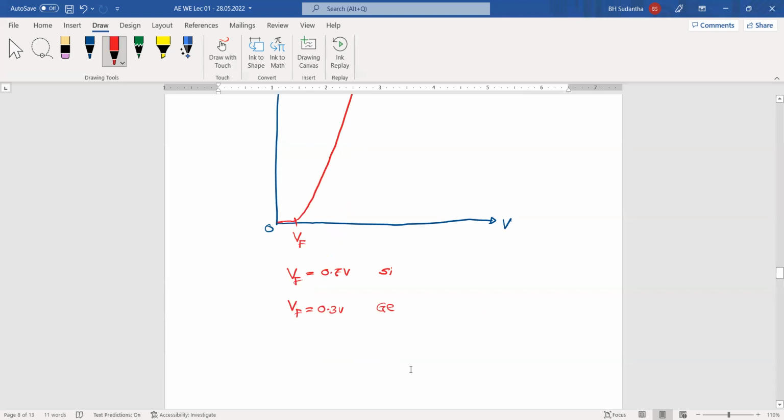You know that using silicon and germanium we can make both N-type and P-type semiconductors, and we can make a PN junction using these two types of elements. The silicon semiconductors and germanium semiconductors have very close characteristics, but some voltage levels and values may be different. For silicon junctions, we need 0.7 volts to break that potential barrier, and we need 0.3 volts if the material is germanium.